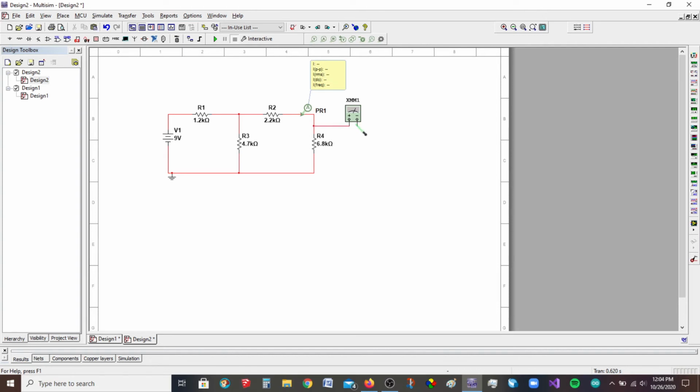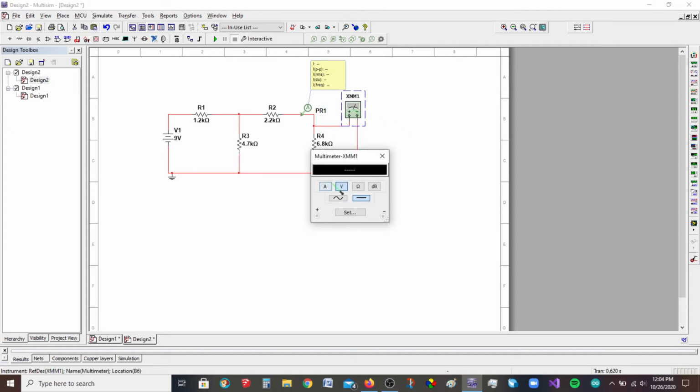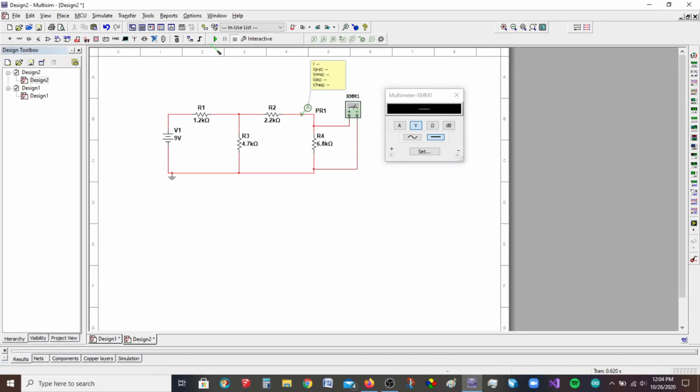Add a voltmeter here. I could always just put a node voltage probe in there because it's referenced to 0 down here on the other side of this load resistor. But I'm just going to put a multimeter in, just to make it easy. And there we've got essentially 4.90, right? So it's rounded up just a touch, but I think that's exactly the same.